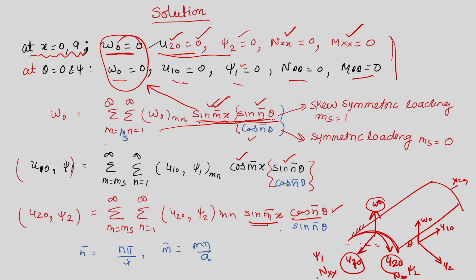So, this is the most important part. Generally, in most cases the skew symmetric case is the problem solved in the literature. For the symmetric case it becomes further special, basically independent of theta, and then the axisymmetric case can be done. So, the problem is simpler. The more general problem is the skew symmetric loading, where the loading is expressed like this.